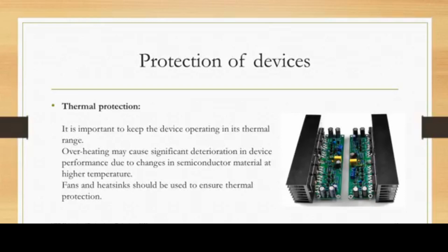Whereas in high power applications, the devices are more effectively cooled by liquids, normally oil or water. Water cooling is very efficient and approximately 3 times more effective than oil cooling. However, it is necessary to use distilled water to minimize corrosion and antifreeze to avoid freezing.